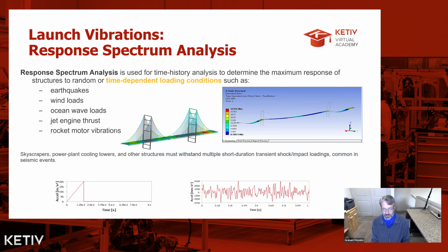And this is where I have a shock wave or a random or a time-dependent loading condition. Here we have an acceleration pulse. And then I want to see what's the maximum response of my structure to that pulse to make sure it can withstand that shock loading. And typically this is where people stop in terms of this sort of launch analysis.